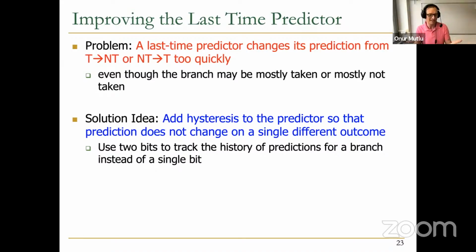And people may become upset, clearly, if the heater and cooler are always working, not to mention that it's very energy inefficient. So the idea to fix this problem is to add hysteresis. And the hysteresis could be very simple. I'm not going to switch to cooling or heating based on a very small deviation from 20 degrees. I'm going to wait until I have enough evidence that the temperature is rising or falling significantly. For example, I will wait until I make 3 measurements, and those 3 measurements say that the temperature is getting close to 21 degrees, right?